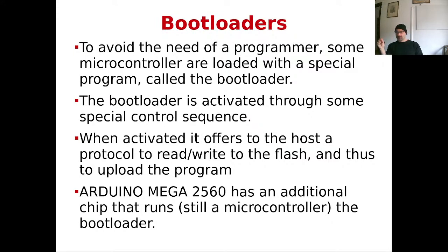So basically, outside of the serial line, before the microcontroller, there is some sort of chip that listens to what bits are coming, and then if it detects a specific signal, it calls an interrupt on the chip, that then starts executing an interrupt service routine that puts the microcontroller in listening mode, and in this way it can read and write the flash.